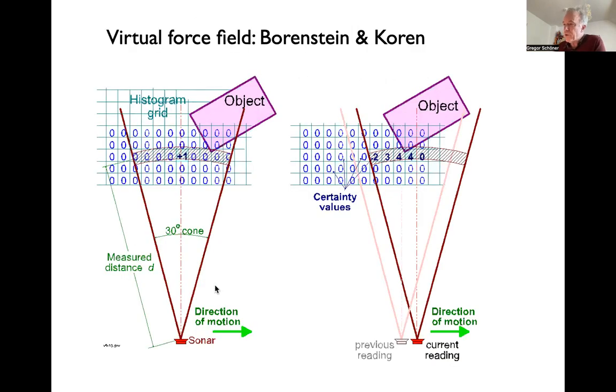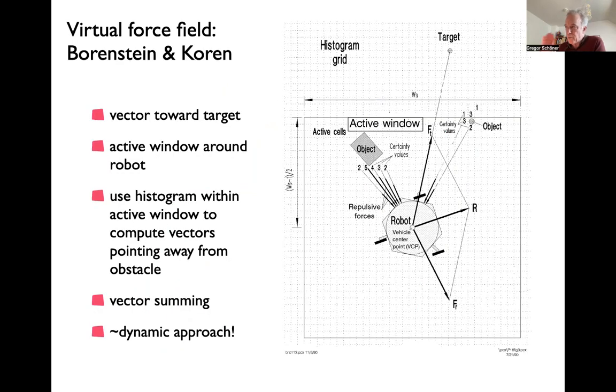I'll maybe just show you. So for instance, here you have the vehicle moving, with the sonar, it's looking here in a particular direction, and it will be accumulating ultimately information about pixels in the world where there might be a surface. For instance, under these conditions, it might enter here a reading, and then as it moves along and has gotten an echo from this object, it would add readings, for instance, at that distance and these different angles, and that would be what contributes to a histogram of how often there is evidence for some obstruction in a particular location in the world. So it encodes both the direction and the distance in which that happens.